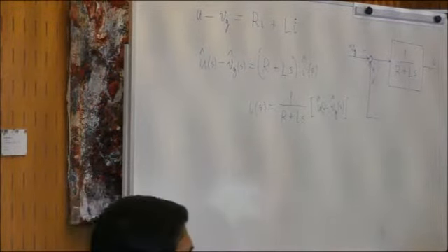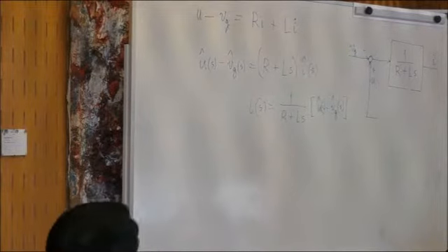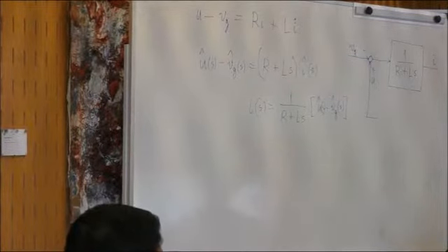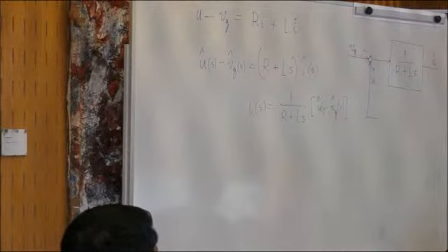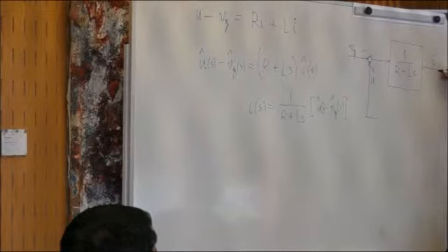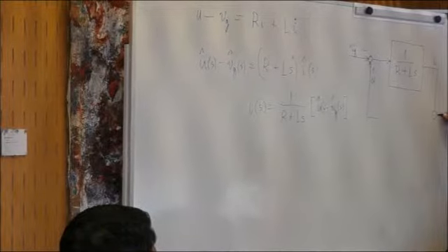Okay. So now here we have a reference signal. I told you earlier, meanwhile I deleted, that we want I to be proportional to the voltage Vg. So we have a reference voltage, we compare I to the reference, which is proportional to Vg, so minus plus to compare them.